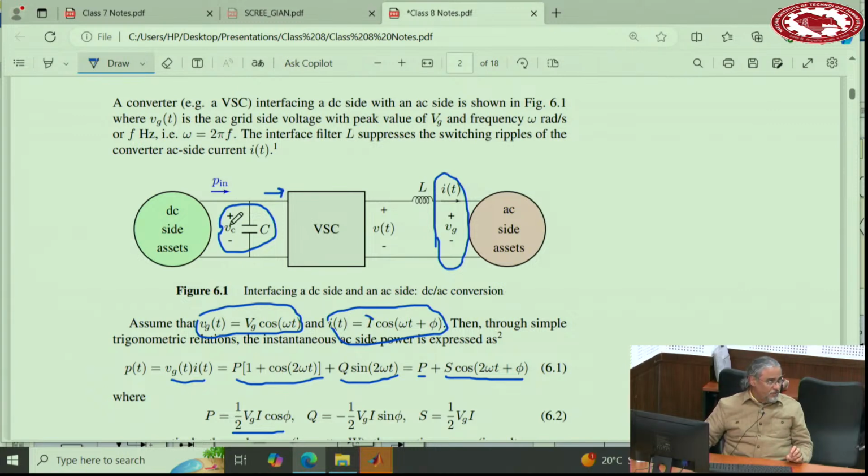But a 20 millifarad capacitor of 500 volt is a huge device. And not only is it huge, it's very expensive. And also it has a lot of issues, particularly reliability, because you need to use electrolytic technologies, which do not operate very well in outdoor conditions for capacitors. So this obvious solution is not very attractive.